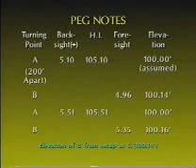Assuming an elevation of 100 feet for point A with a backsight reading of 5.10 feet makes the HI 105.10 feet. Reading a foresight of 4.96 feet and subtracting that from the HI gives an elevation of 100.14 feet for point B. After moving the level, the new backsight reading is 5.51 feet with an HI of 105.51 feet.